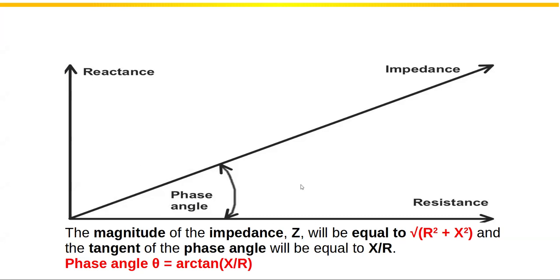And that angle is going to be the arctangent of the reactance divided by the resistance. So when you have a 45-degree angle, you've got some resistance component. And they're equal: the resistance and the reactance are equal. Nothing special about that. No. Okay.